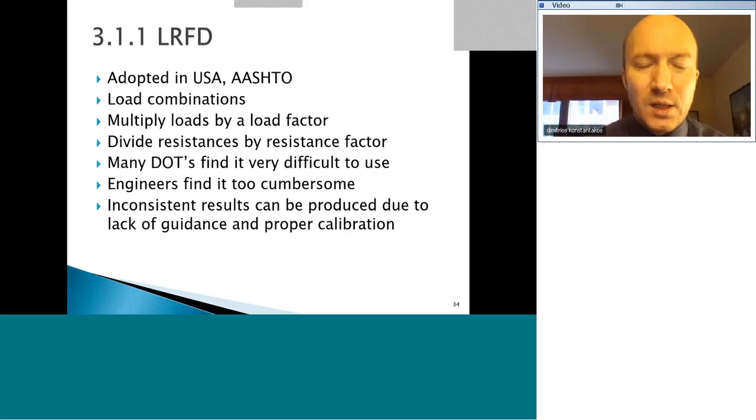Now let's look into LRFD, load and resistance factor design. As we said, it was adopted in the United States, especially by AASHTO. And the reason they have adopted it is because they have all these bridges where there are all different structural combinations. So the idea is that you combine loads, you multiply loads by a factor, you divide the resistances by a resistance factor, and it tends to be quite cumbersome.